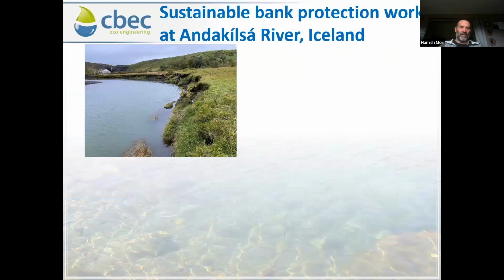So here's the site as it was eroding. Here's the powerhouse from the hydropower scheme here. This is a little bit deceptive. This bank is actually about 4 meters high, and it's about 4 meters depth down to the base of the river. So very significant bank erosion. Since the erosion started, it migrated about 50 meters over to the right here.